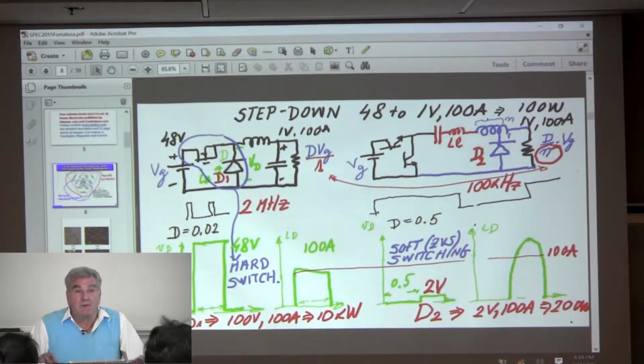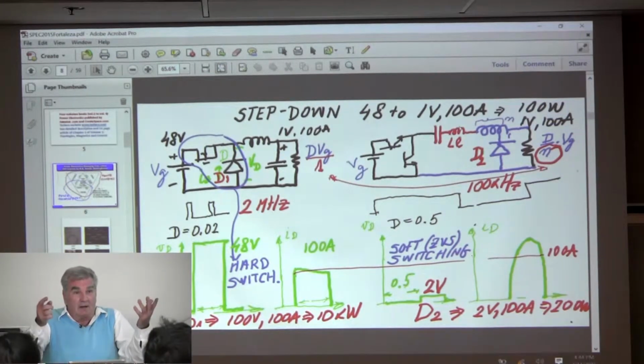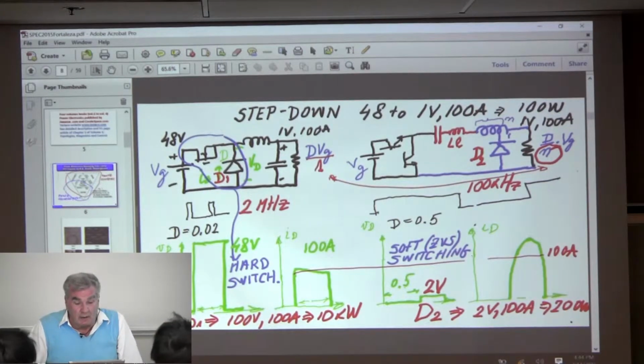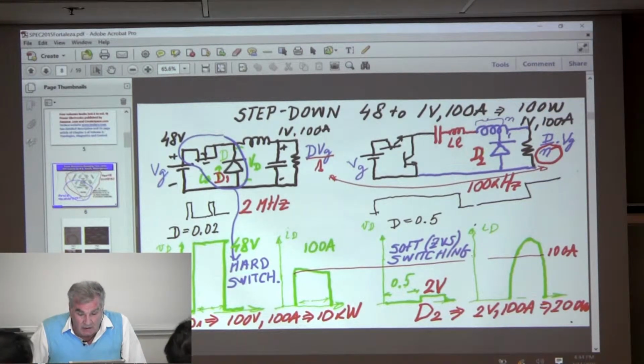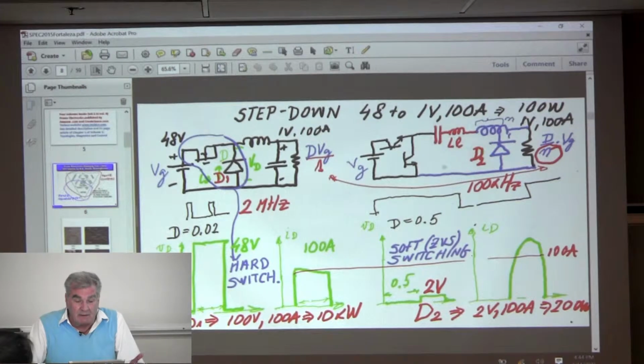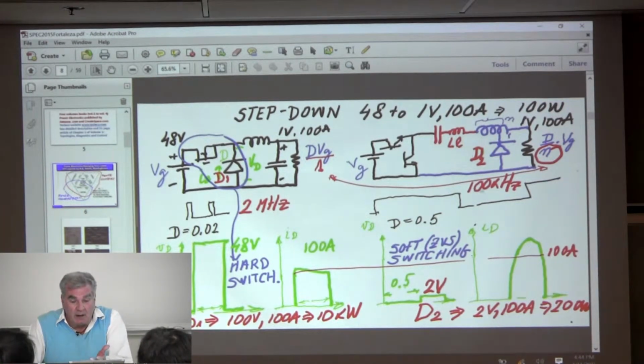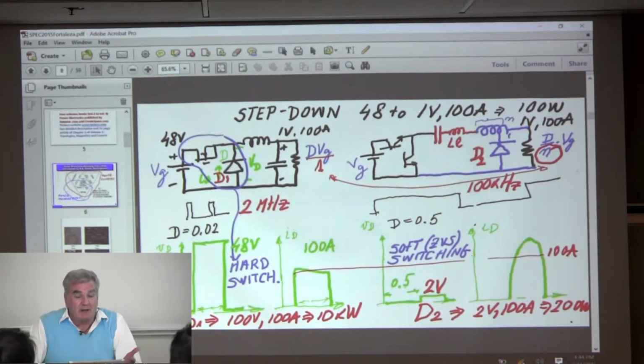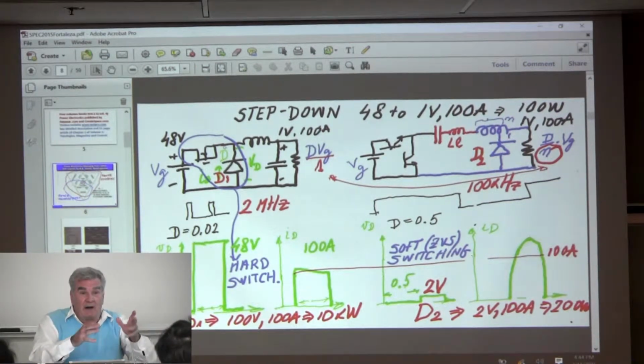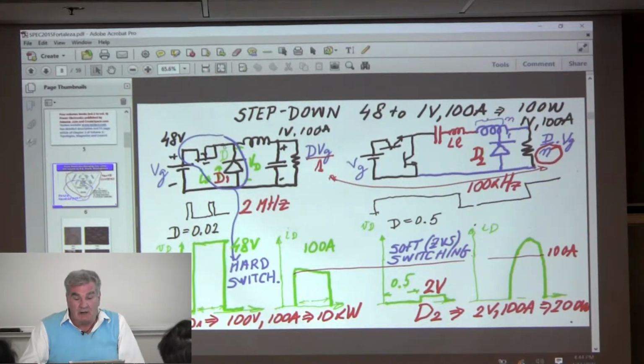Here, this capacitance is part of the circuit and resonates with it when it needs to, and so that is really not any more lossy. So basically this now can operate at 100 kilohertz, be much smaller, have much lower cost, but it has 3 devices, and it has zero voltage switching, has all of the things here. And yet industry now has to use 8 of those in parallel to make a fast transient response. Here, in this one, I can use just a single stage and get a fast, quick transient response, okay?